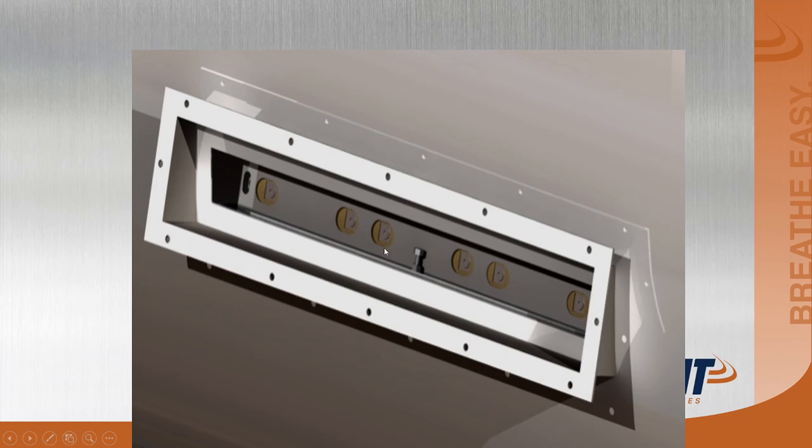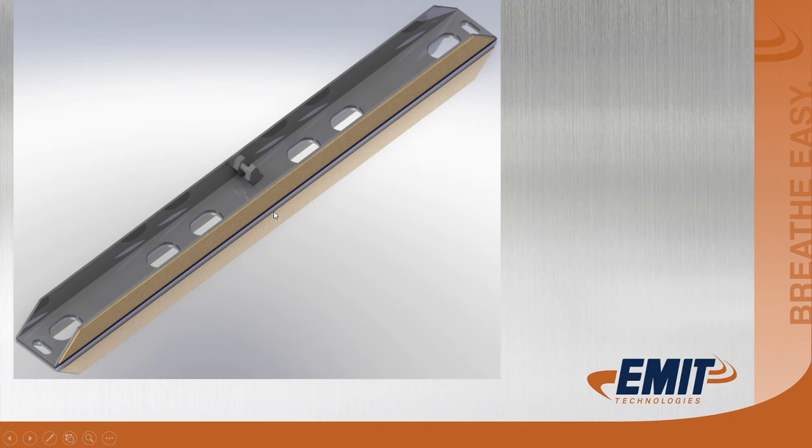There's what it looks like when it's assembled. Here's a picture of the channel cap. Again, we've got a bolt in each end, and this forcing screw pushes on one bulkhead and it seals on this side where the gasket is. This gasket is the same gasket that we wrap around the catalyst elements. Again, it comes in a roll and it's got an adhesive back on it. You cut it to fit.